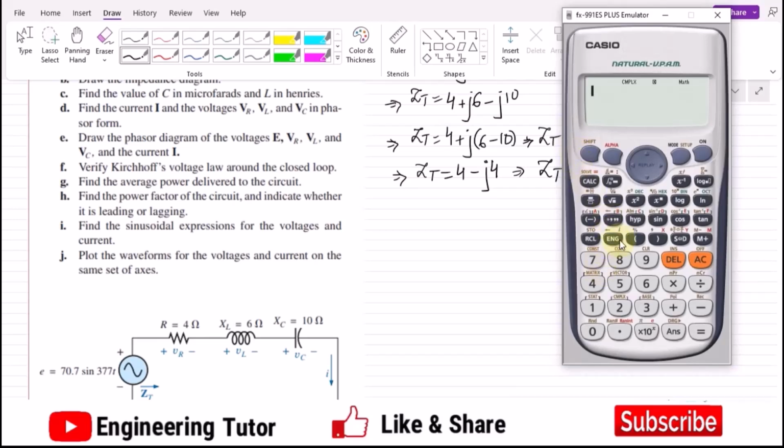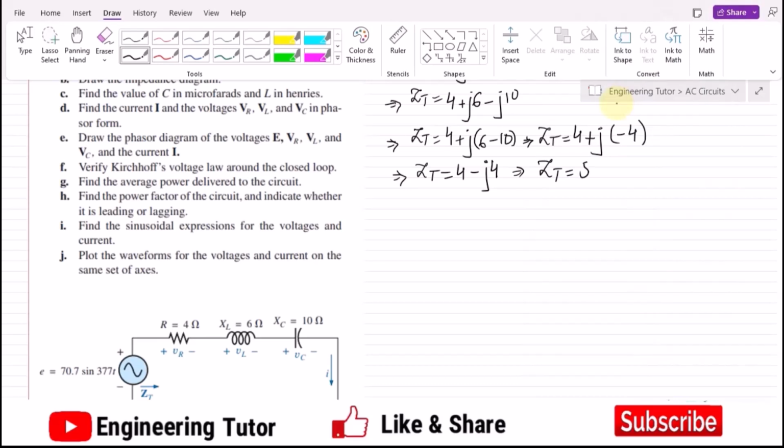So again coming over here and writing 4 minus j4, now converting it into the polar form, it will be 4 square root of 2 at minus 45, or it will be 5.65, or it can be 5.7 ohm, and the angle it has is minus 45 degrees.